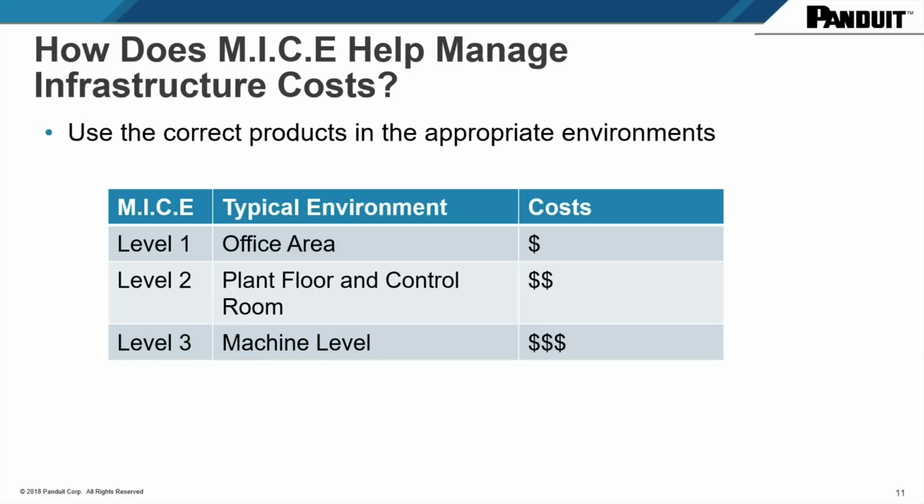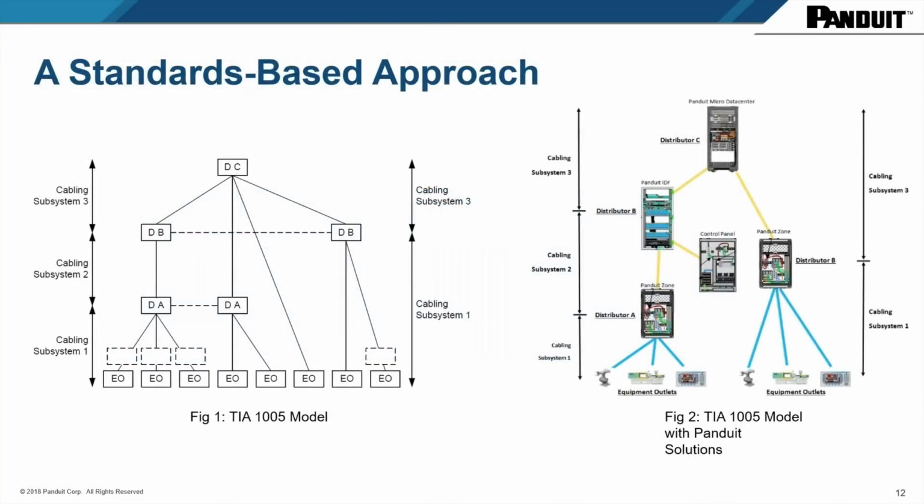So we could potentially be using commercial grade product inside of a factory if we have the right protection for each and every one of those systems. Enclosures, for instance, can be those types of protections. So inside of an enclosure, you could put commercial grade product as long as the enclosure is made out of stainless steel and it's got the right gasketing so water and dust cannot get into these systems. So these are the things we will always apply, which is common sense when we're running these systems.